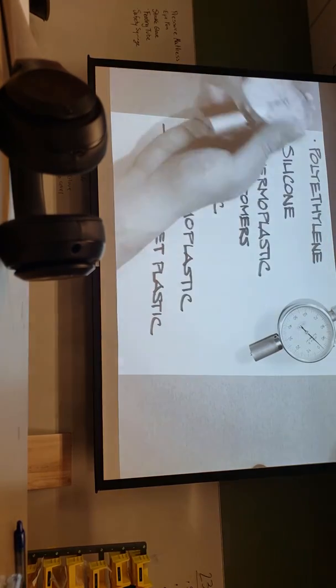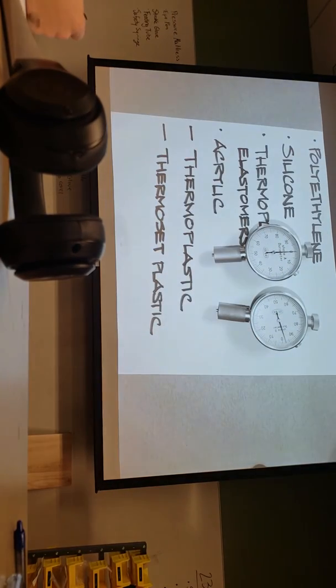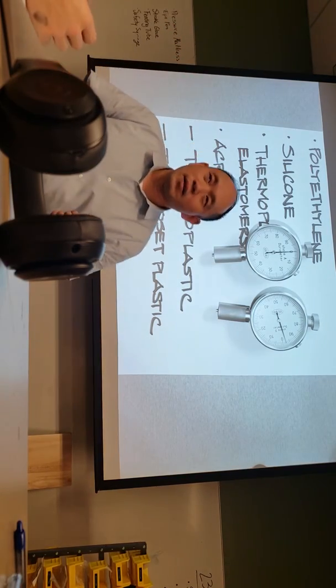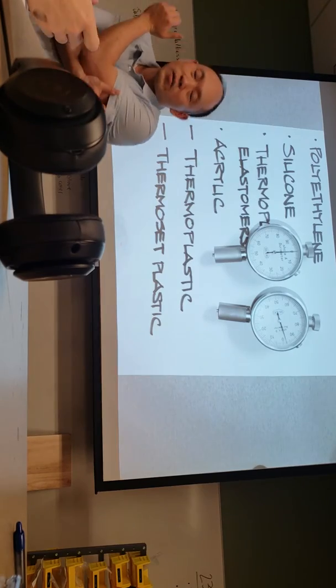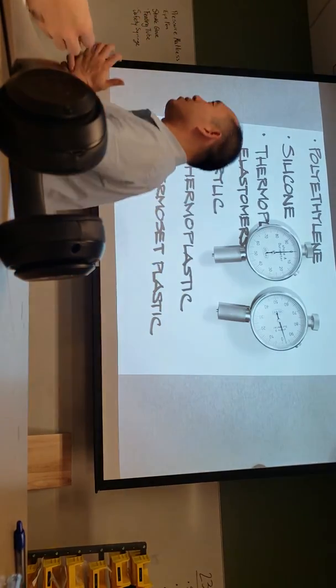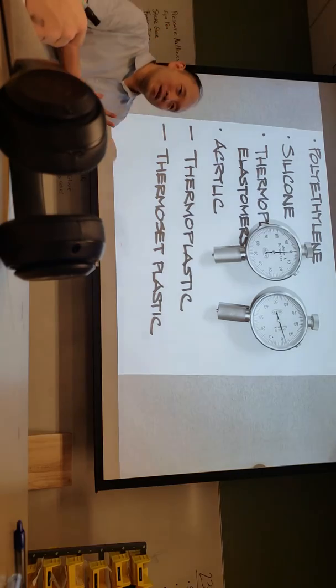So you can see the higher the number, the higher the stiffness. So if you do want to characterize some of your materials in terms of hardness, then you can use those durometers as well. They don't really correlate to any particular known unit, but it is a standard.